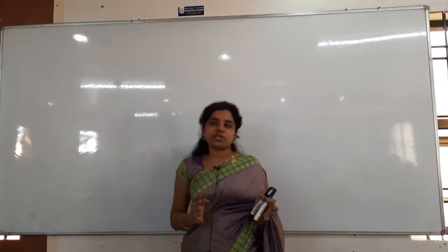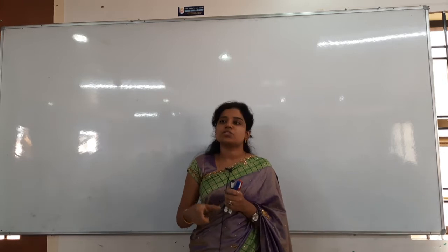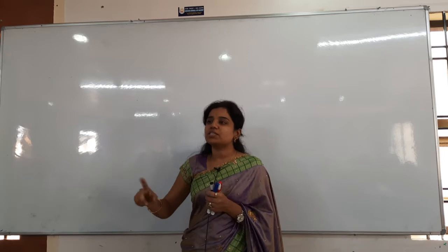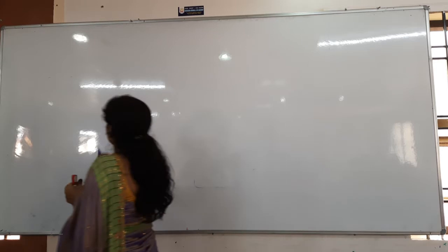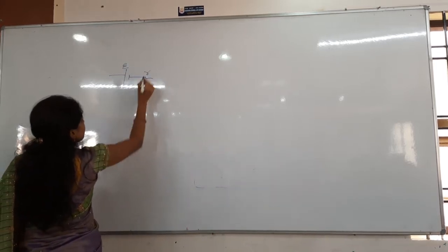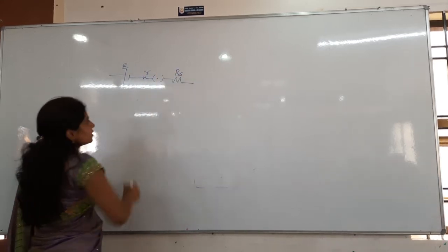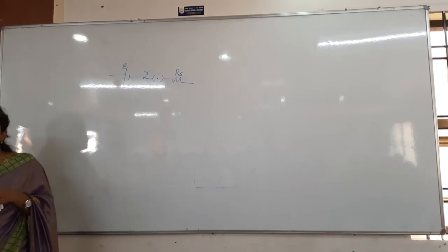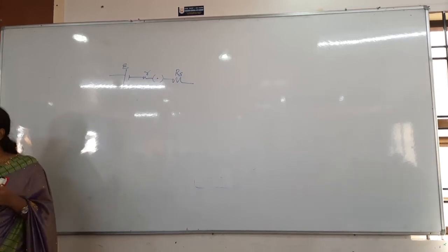Now in this potentiometer there is a principle. What is that principle? The potential difference is always directly proportional to the balancing length, so V is directly proportional to L. Balancing length means here I have the potentiometer like this, operating EMF is E, and the internal resistance R, a switch is there, and then a series resistance, otherwise we call it a rheostat. Rheostat or series resistance, everything is just a variable resistance only.